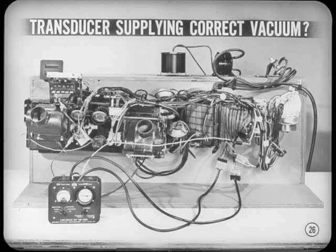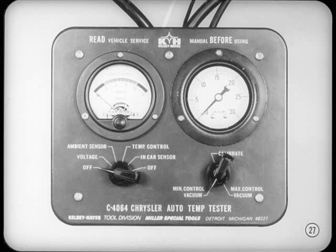The first test to make is to determine whether the transducer is supplying the correct control vacuum to the water valve thermostat and the power servo. If control vacuum is not accurate, none of the other components can function properly. Set the instrument panel temperature selector at 75 and the tester voltmeter on off. Start the engine and set the idle speed at 1000 RPM.